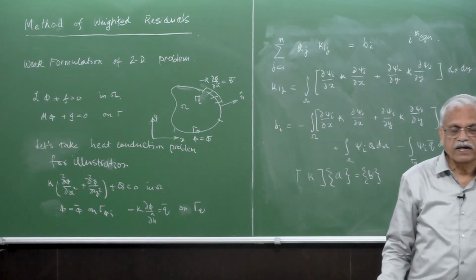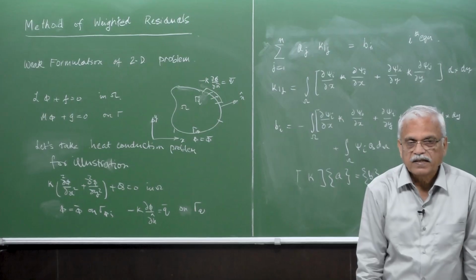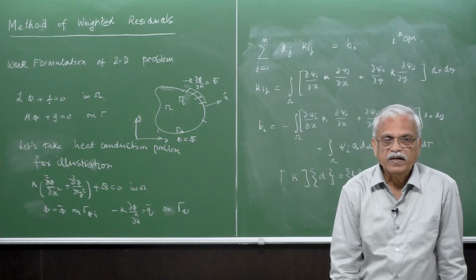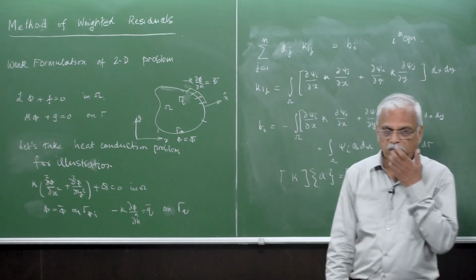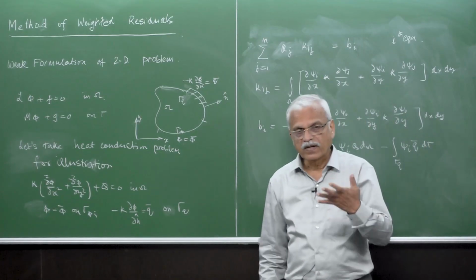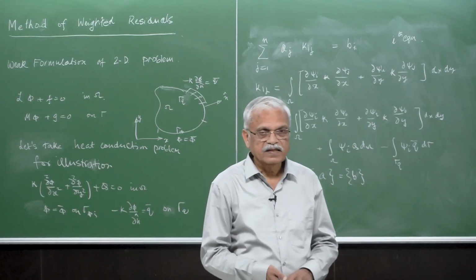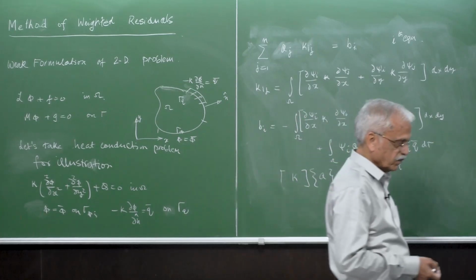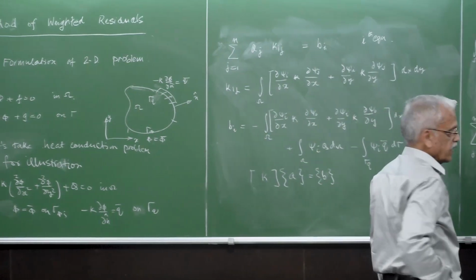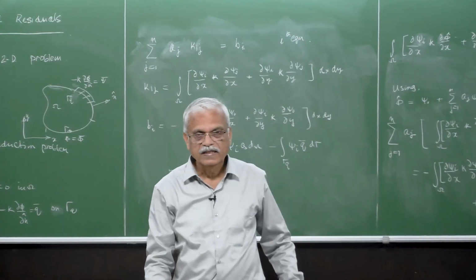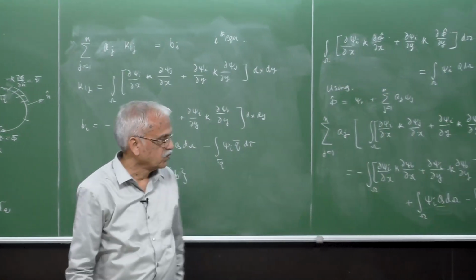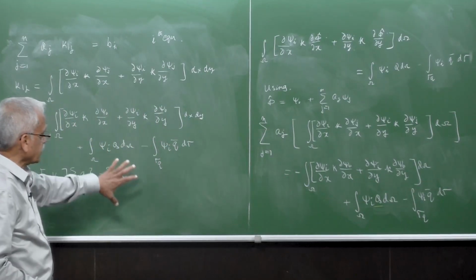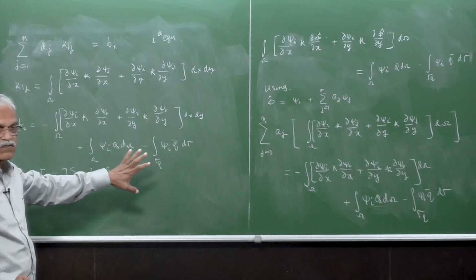Number two, the advantage of the weak formulation is that we are able to take the residual on the derivative boundary condition into the weighted statement, and we are able to cancel the evaluation of the derivative on the boundary with the derivative term which has come out of this integration by parts. So finally, this is a very appealing representation of the weighted residual in the weak form.